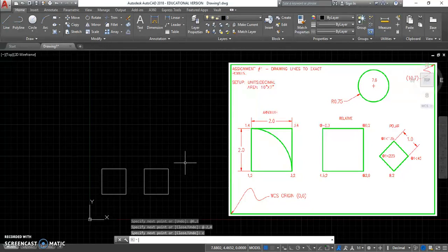And that confirms it. Our next style that we're going to work on is a polar coordinate. AutoCAD has polar coordinates, and what that means is we type based on angle. So to show this, we can click through coordinates here with our line command being on. Notice it turns off, click again, it's back on, click again, off, on. So I haven't started the line. In order to specify the first point, I'm going to go ahead and say 8, 2.